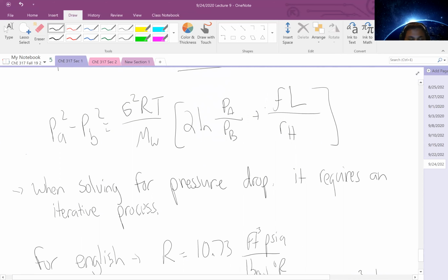But that's really compressible flow. As we explore it, we have the 3 situations: isentropic, adiabatic, and isothermal. For isentropic, we have the expressions that let us look at comparison of values, pressure, temperature, velocity, and so forth, based off of what we knew in terms of our Mach number. For adiabatic and isothermal frictional flow, we have a couple of expressions that take into account those losses, the frictional dissipation.